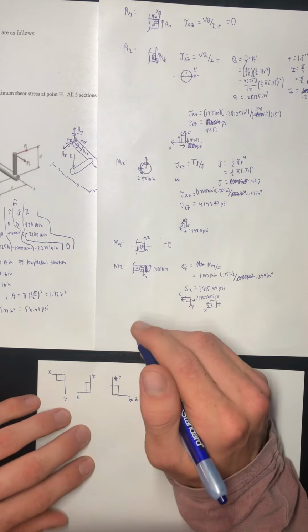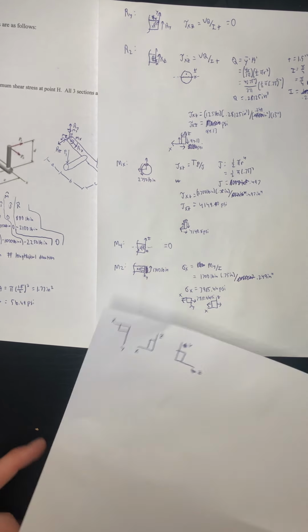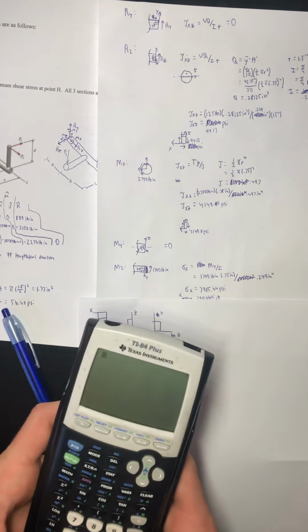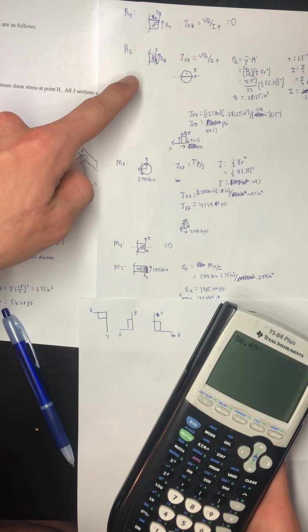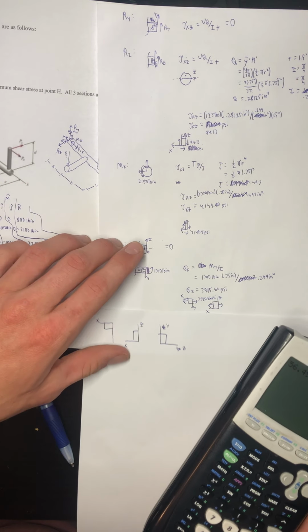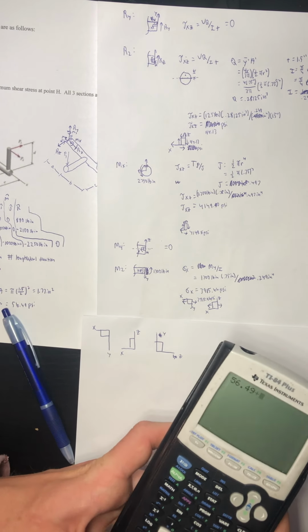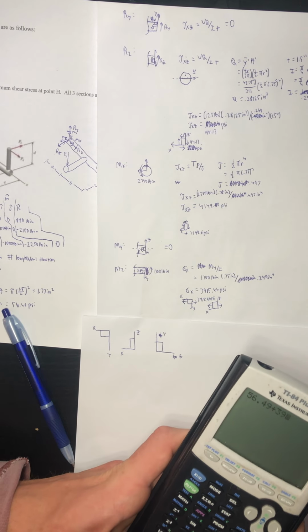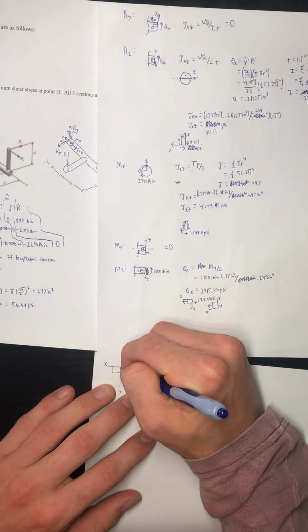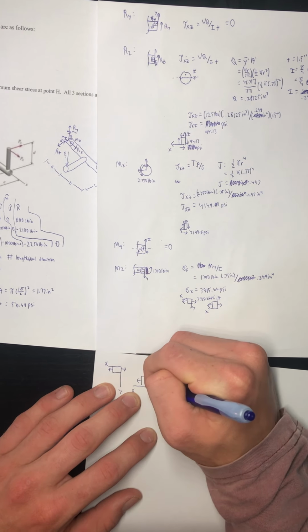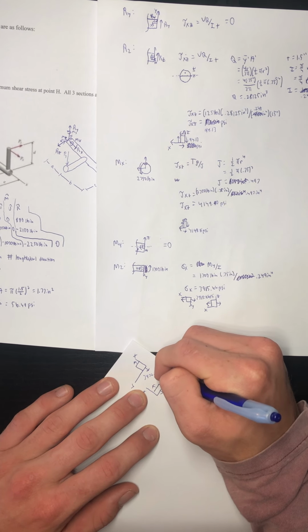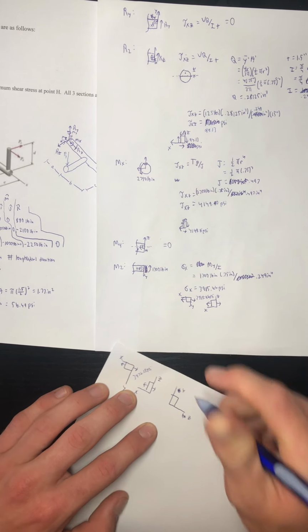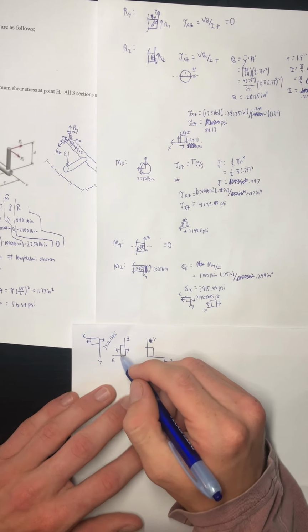So from this block, we have 56.49 psi acting in X, acting in tension. Otherwise, we have this tensile force that results from bending, which is 3,915.66 psi. So that gives us a total of 3,972.15 psi acting in tension. So that's going to be our sigma x.